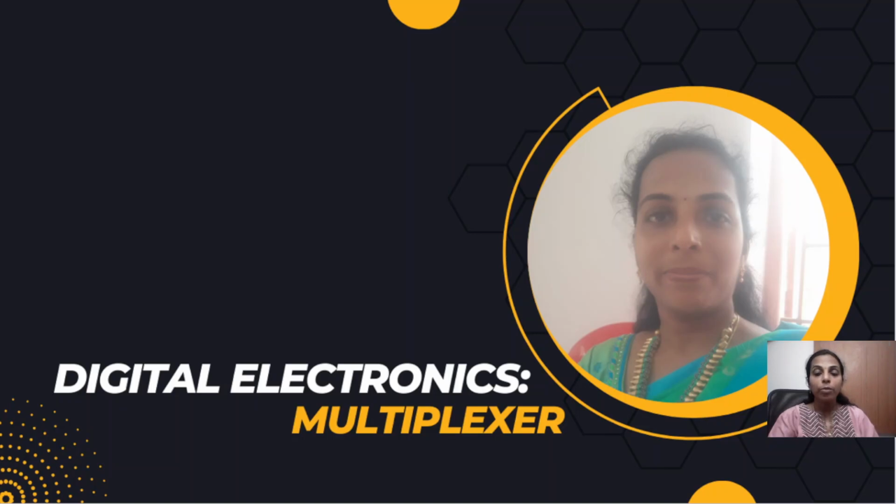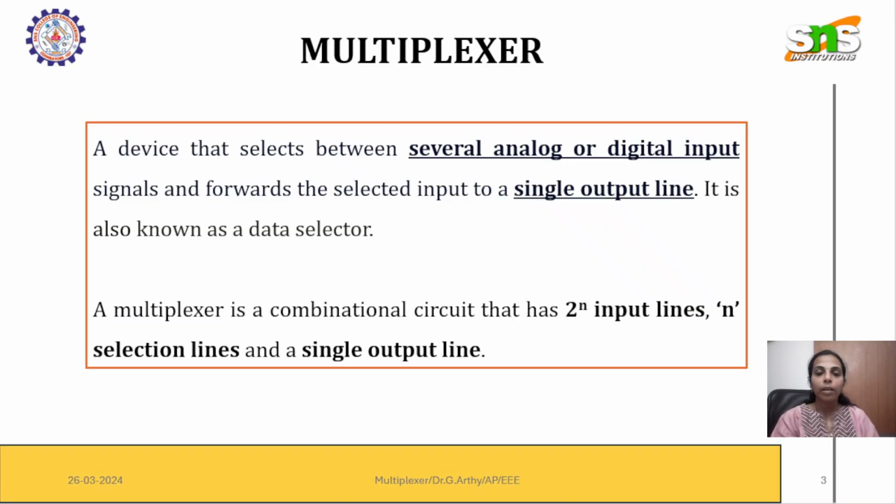In today's session, we are going to discuss the multiplexer as a part of the digital electronics lecture series. A multiplexer is a device that selects between several analog or digital input signals and forwards the selected input to a single output line. It is also known as a data selector.